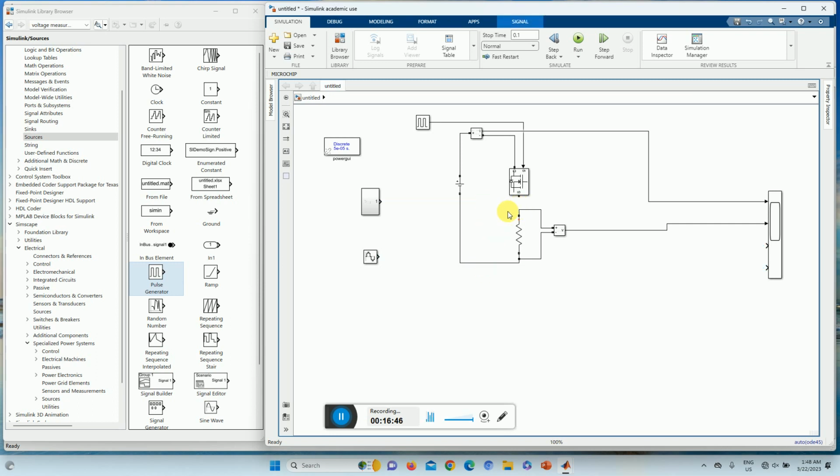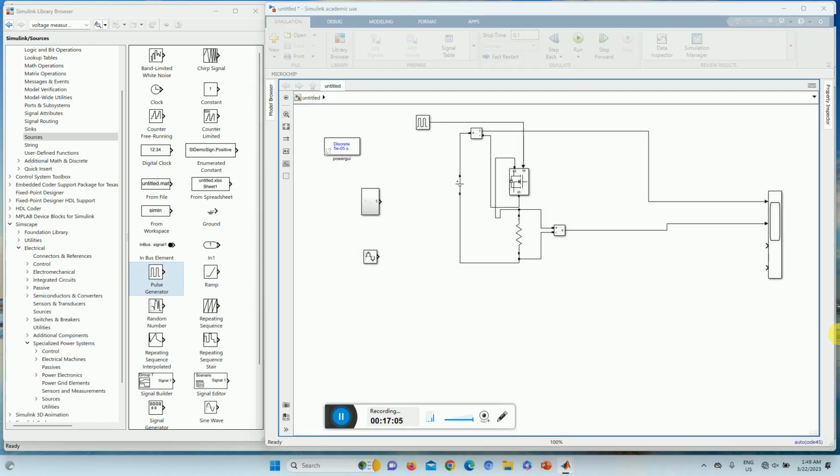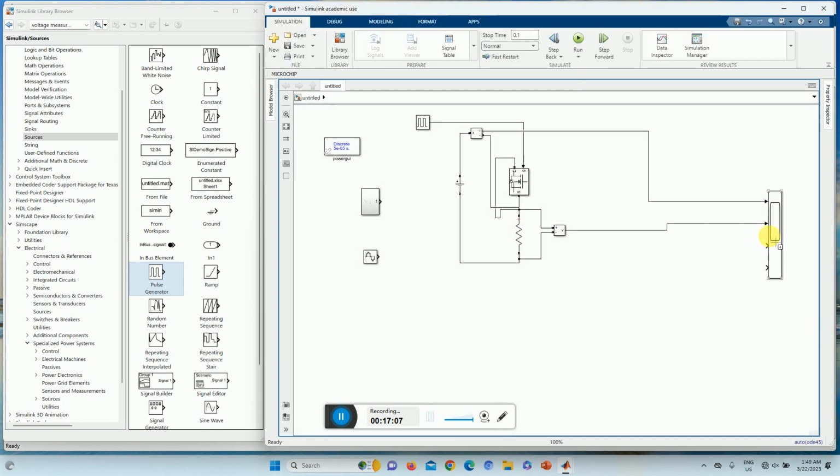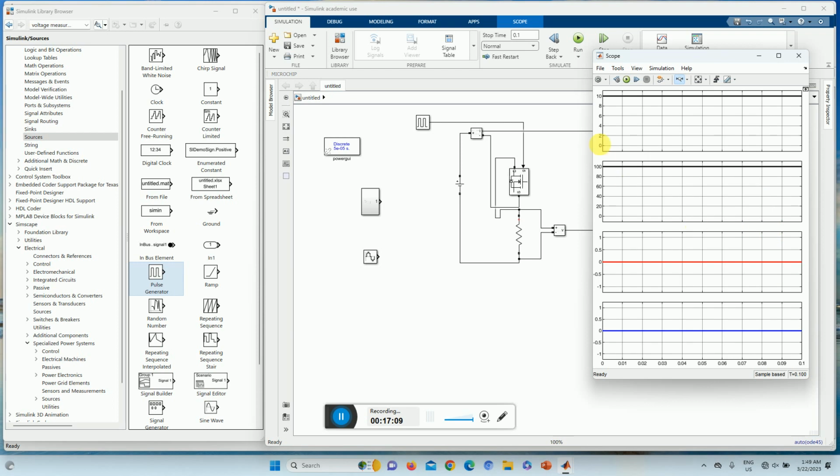What we want to do is a little bit of play with it. So let us say instead of having this connection, I will just do a reverse in the connection, like we are connecting to the source, and this drain part I will connect to the resistance. If this is the situation, how does this MOSFET behave?